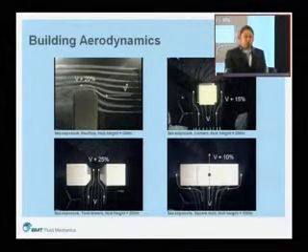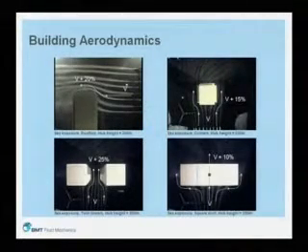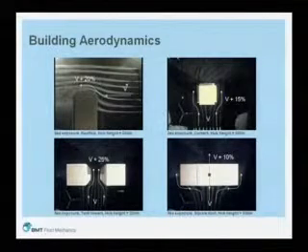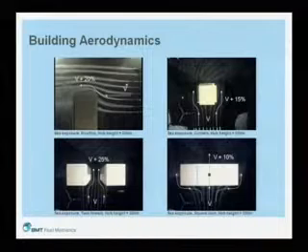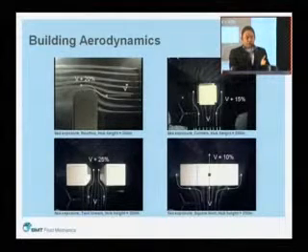The other thing you need to consider is building aerodynamics, because there is speed up as the air moves around the building. You need to think about where you're going to put them. Ideally, you want to put them somewhere where the wind speed is high, so either flow over the top of the roof or around the corners, or if you have a twin tower arrangement, considering putting turbines in between the towers is interesting.